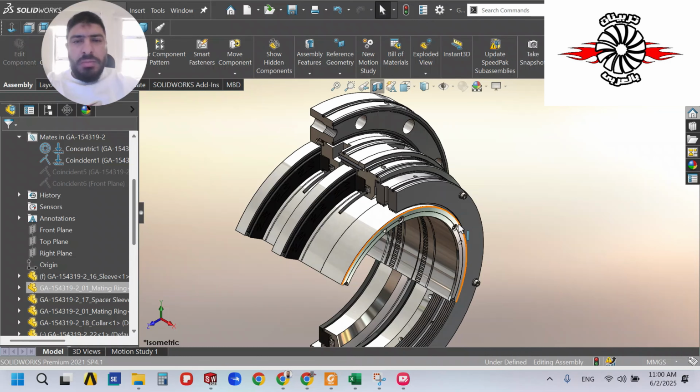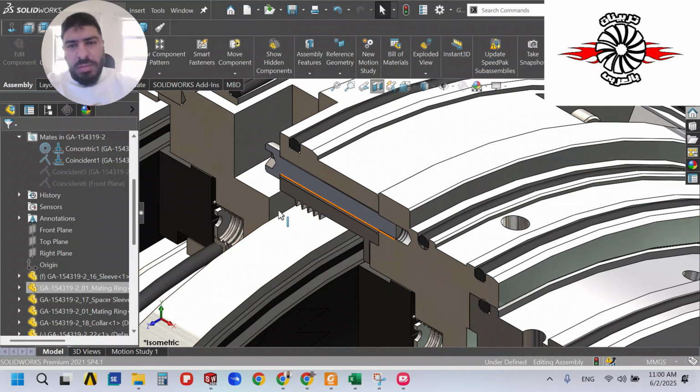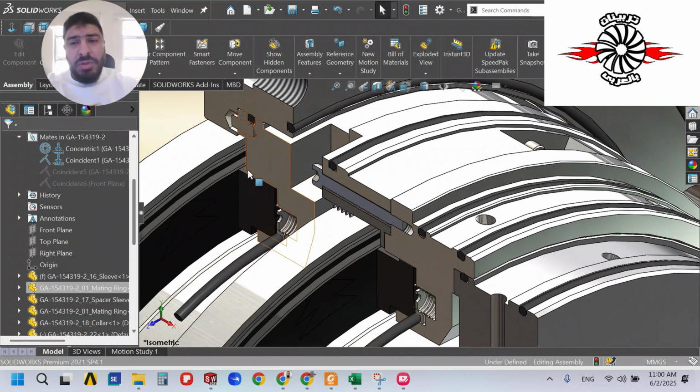Also, we talked in the previous video about that drag seal. This is a tandem type seal with intermediate labyrinth, as you can see here. This intermediate labyrinth is to minimize and prevent any leakage coming from the seal gas or process gas going to the atmosphere side.